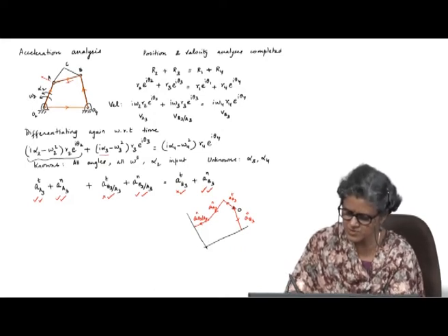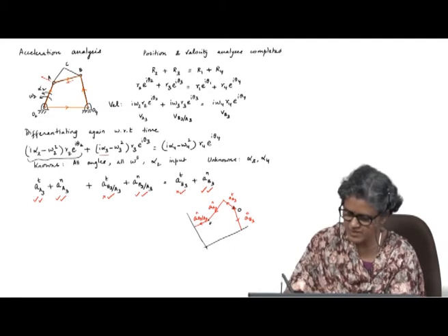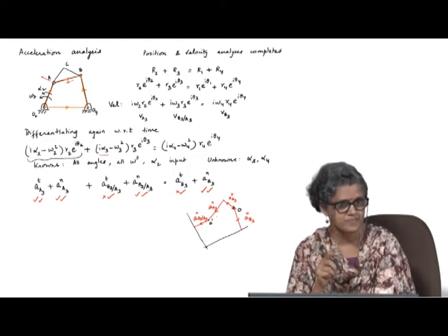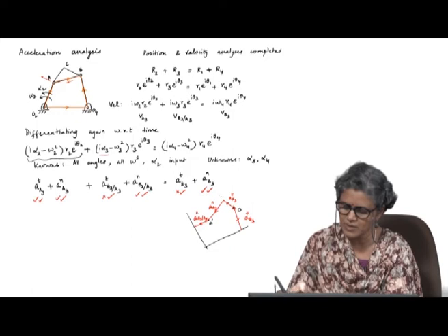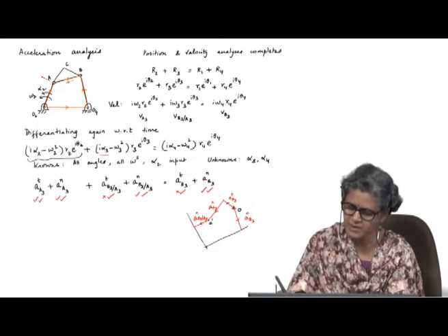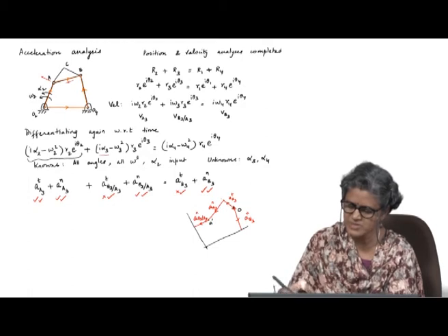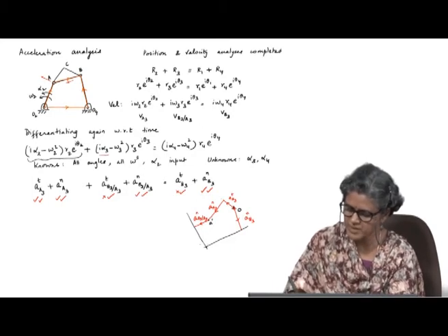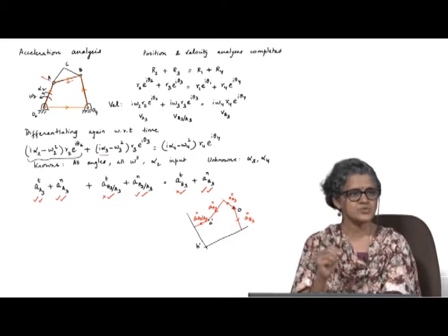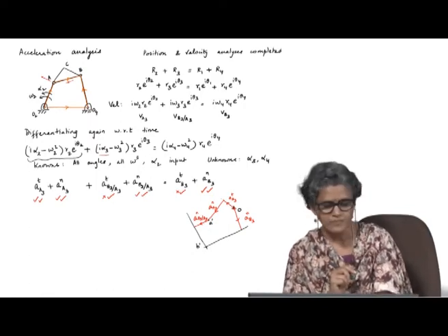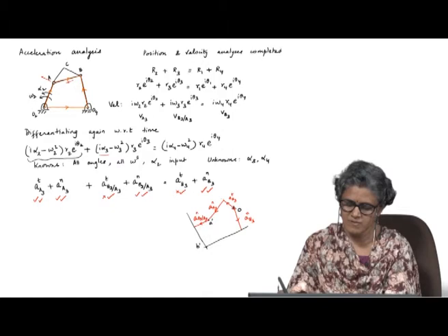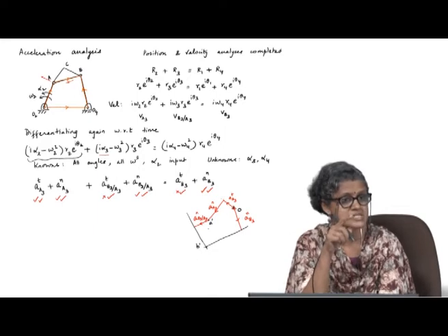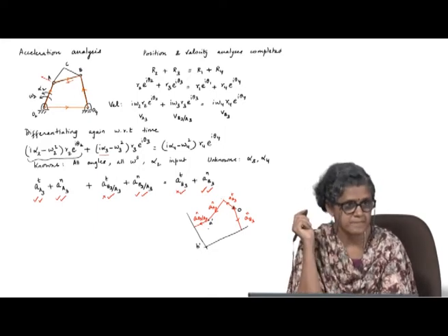Okay, but once I do this now, I get this point, let us call it A dash, small a dash for the acceleration. Okay, this point here, the whole acceleration of A was completely known, it is this plus this. So, this point is A dash and I added the relative component there. So, this point here will be B dash, the intersection of these two will give me B dash. So, if I draw a vector from O to B dash, that will give me the absolute acceleration of point B. Okay.